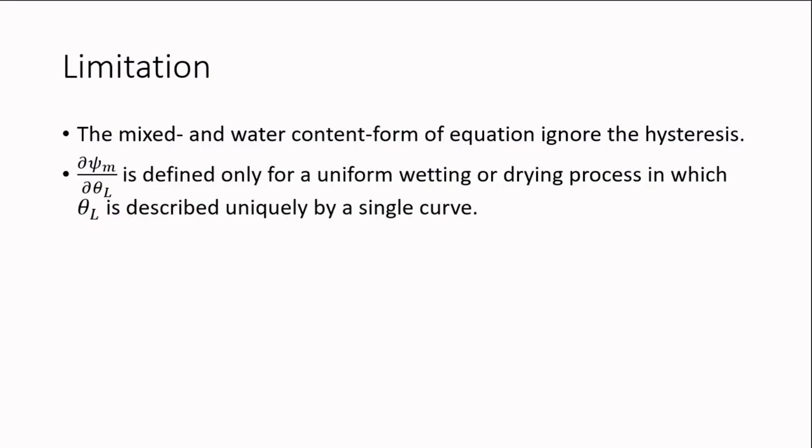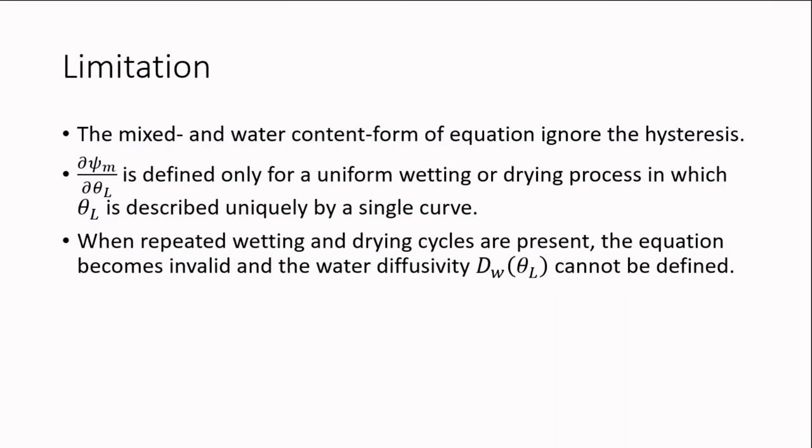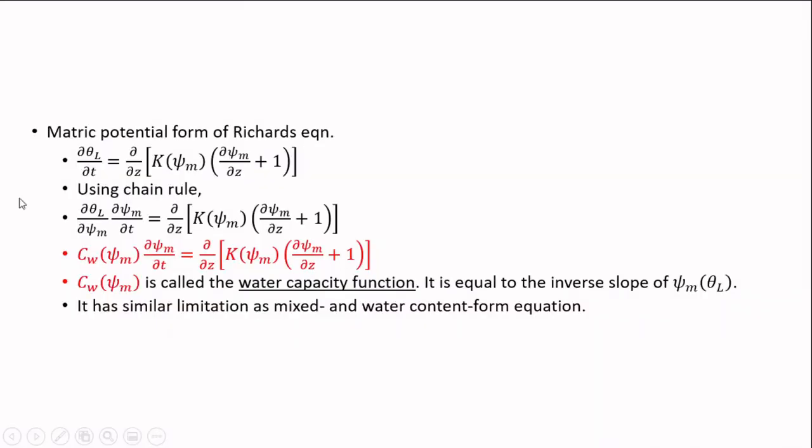So the derivative of matric suction with respect to volumetric water content is defined only for a uniform wetting or drying process, in which volumetric water content is described uniquely by a single curve. We know that there's more than one curve because the wetting and drying are different. So when repeated wetting and drying cycles are present, the equation becomes invalid and the water diffusivity D(θL) cannot be defined.